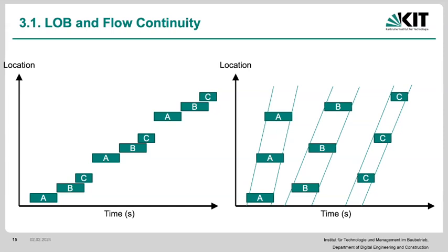And it's shown that this can improve what we call learning curves. Do you guys know that as well? The more you do an activity, the more chances you have of better productivity for that activity. So this by itself means that a crew or a bunch of crews hired for, let's say, concrete, are always going to be hired for concrete throughout the duration of all of the, let's say, 10, 20, or however many units you're going to have, okay?